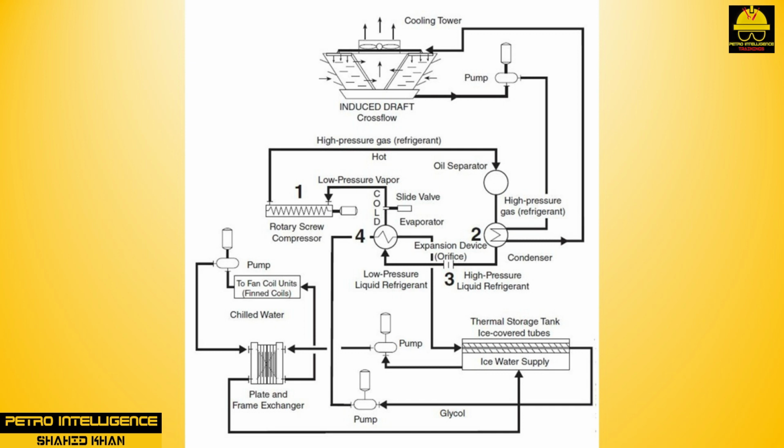When a pound of propylene boils away, it absorbs about 188 BTU, called latent heat. If we pour a pound of propylene into an open container and watch it boil away, a thermometer inserted into the liquid will read -54 degrees Fahrenheit or -47.77 degrees Celsius. The heat for boiling comes from the container and anything touching the container, including the surrounding air. Moisture in the air will condense and freeze on the container and appear as frost.